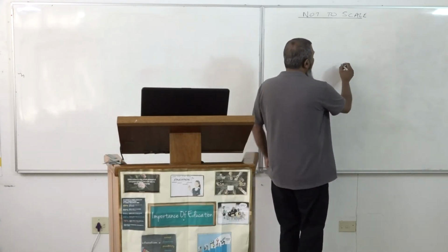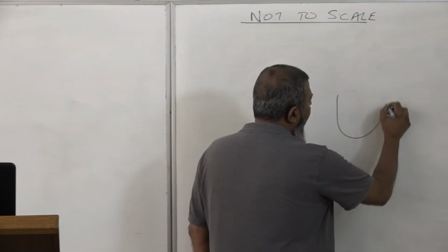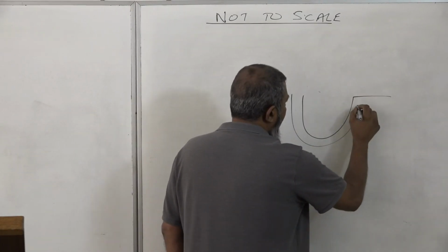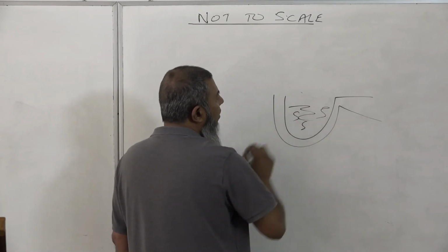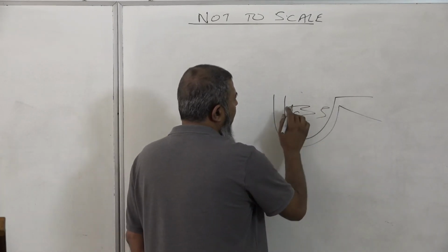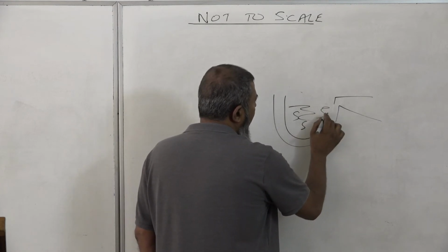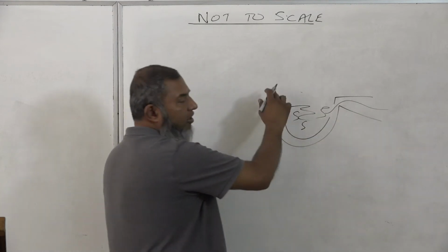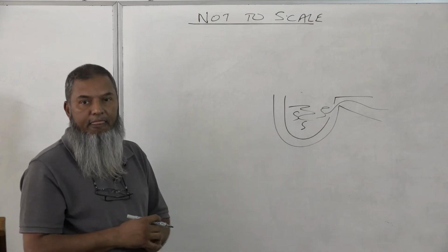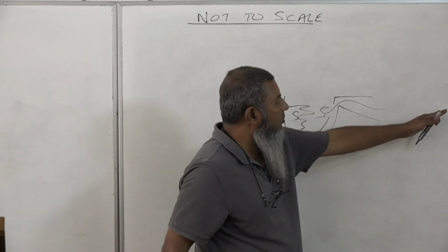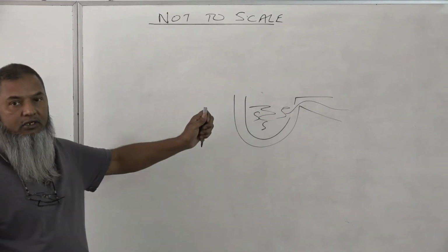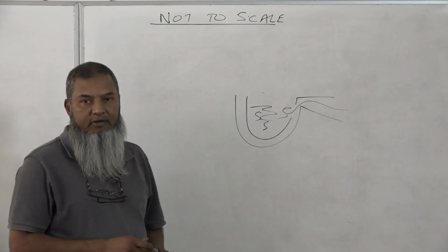It is shaped in a P. Illustration of a P, and if you look at our water closet, it goes like that. So what happens here is the water is always filled in here, always water. When we flush, this water pushes out and comes out, but because it's shaped in a P shape, there's always water in there. That helps us in order for bad, foul smells not to come back to our sewage. So it acts as a trap.